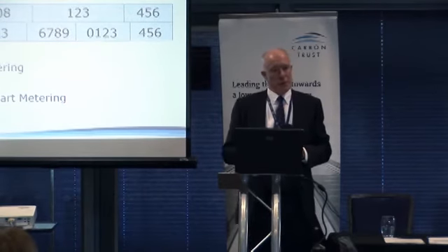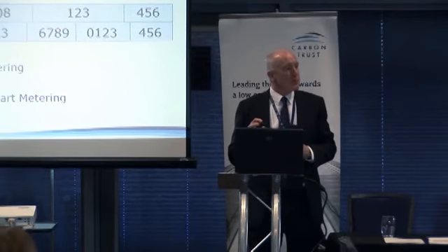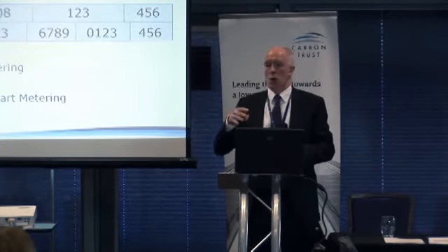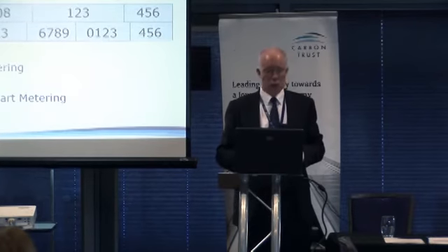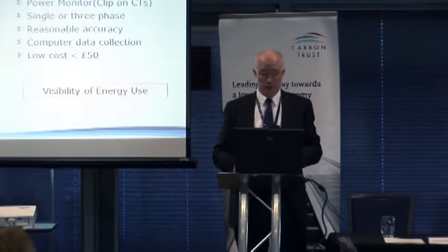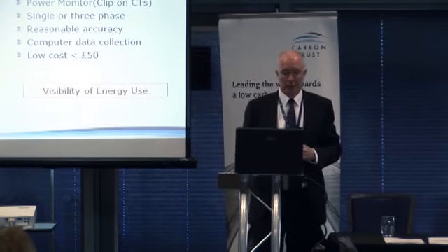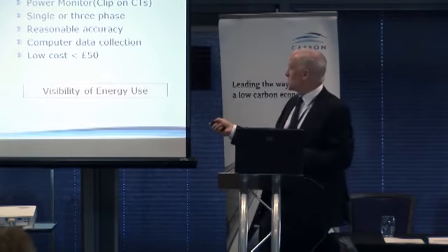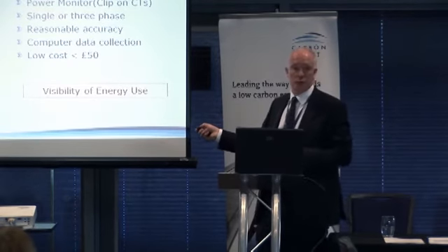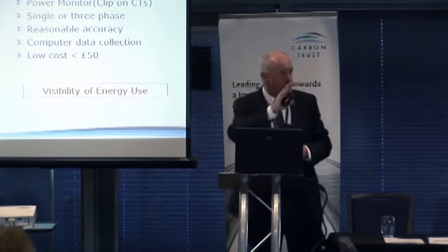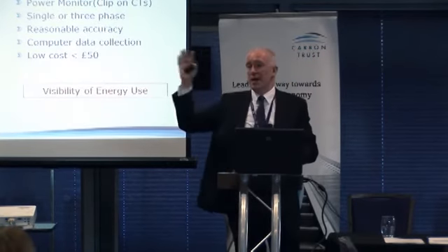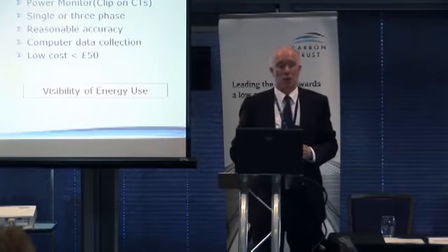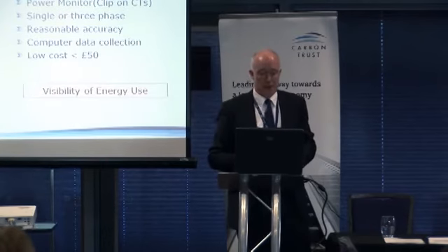If you haven't got a smart meter and you want to do it simply, or you want to break up your electricity to different floors and put an energy manager in charge of each floor, you can use the domestic pseudo-smart meters. These are simple little meters that display the wattage that comes through a distribution board. We can put it on the distribution board here and display the energy being consumed within this particular floor, or however the distribution board is laid out.